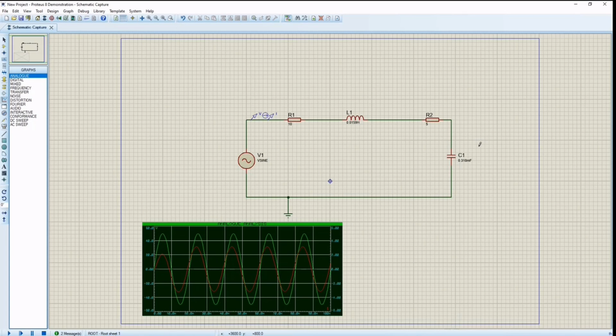We may conclude that the current leads the voltage by 80 degree. This is due to the capacitive reactance being greater than the inductive reactance. The phase angle percentage error is 2.33%, and the current percentage error is 0.07273%. That's all from us.